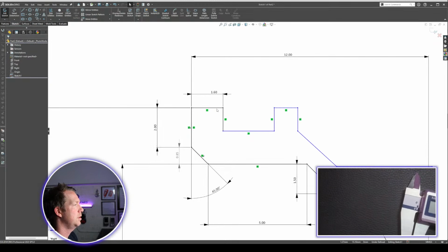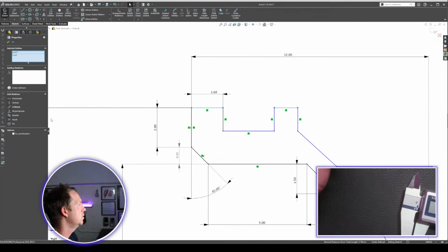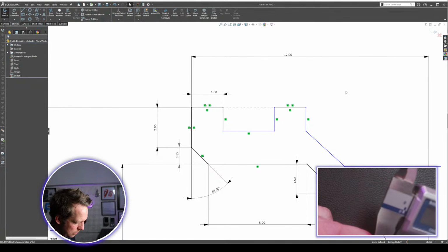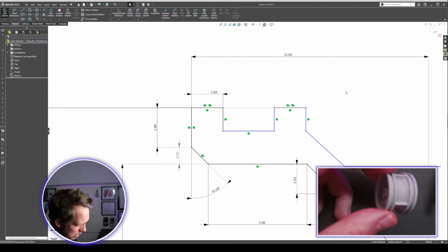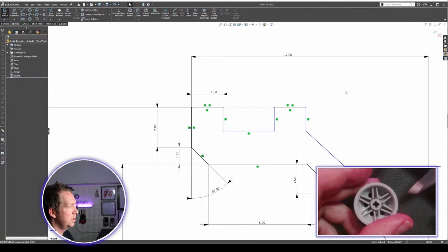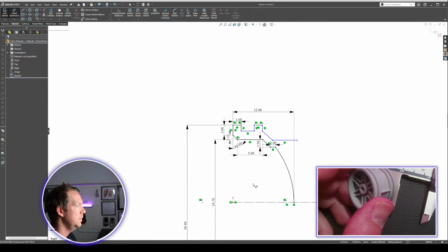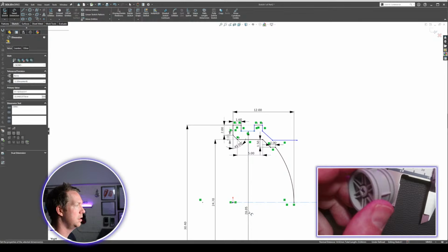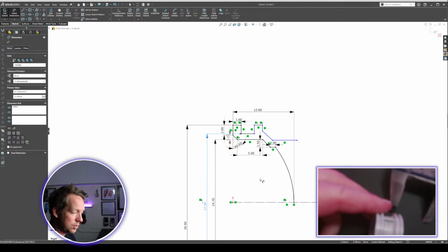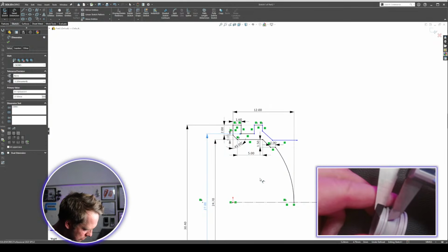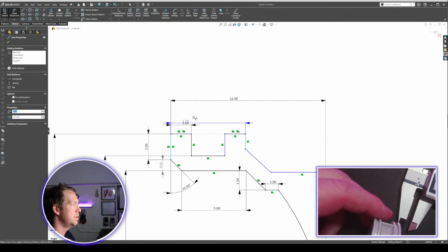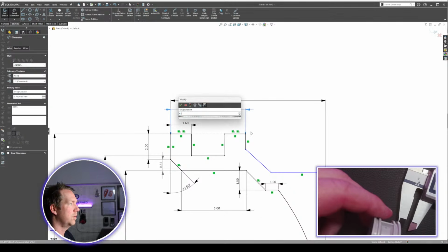So a couple of sketch features we use here. These lines will be collinear and equal. I think they're both 1.6. And then we can measure the in between them, 27.1, 27. So that's this one here. Yep, right. The width between those two gaps to the outside of them, you get 5.3. So that means it's 5.3 there.